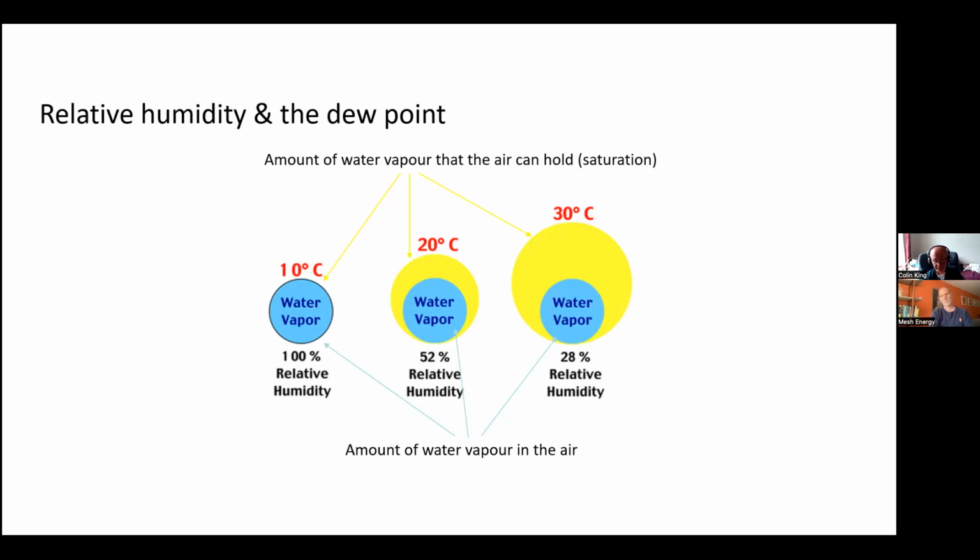But that's why in the Middle East and the Arabian countries and other warmer climates, they don't have issues with mold and damp like we do, because the air temperature is always relatively higher. Theirs comes because of the air conditioning and those other issues. So it's important that when you look at design temperatures for people in houses, that 18 to 20 degrees is not really open for debate.